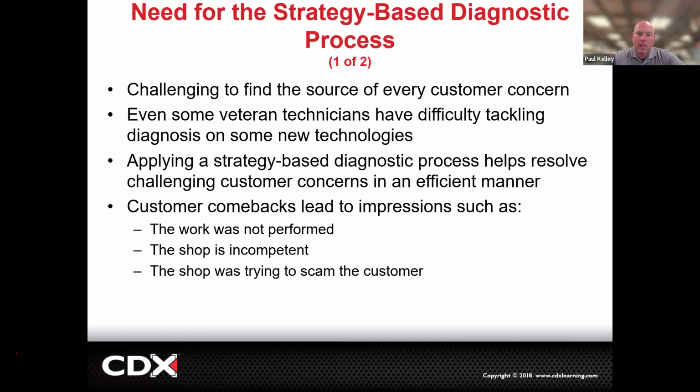The reason that I want to point that out is with AC, it's real easy for you to be like, oh yeah, here's how you do the service. Here's how you do the recover, recycle, recharge. Here's how you replace the condenser. Not hard. But remember, most of the time the car comes in and what's the customer say? What have I been telling? What's the customer say? My AC blows warm. You got to really understand the system to be able to take the customer concern of my AC blows warm and diagnose it and determine what you're going to sell.